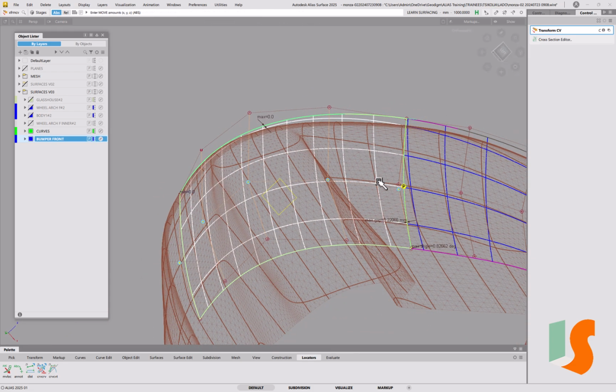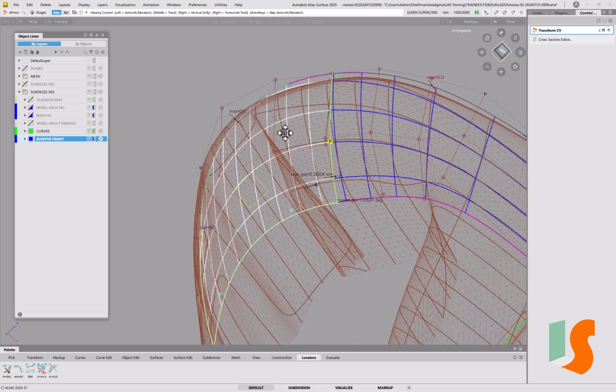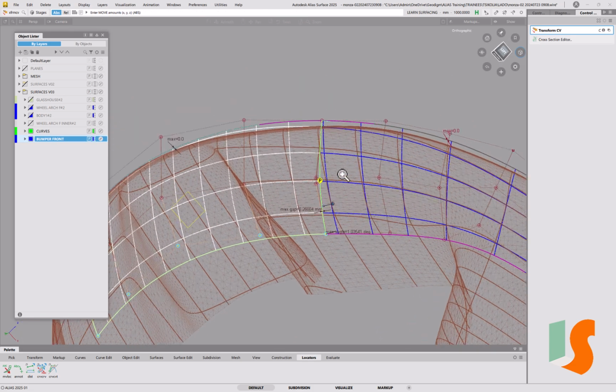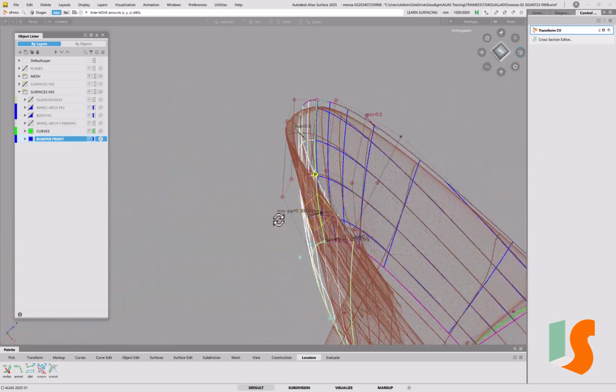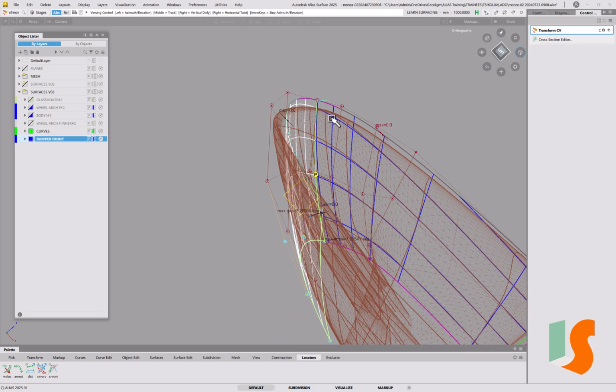similar. Unfortunately, because we are a long way from this, it's going to be pretty tricky, because the original was quite flat, and I've ended up with something that's rather crowned at the minute. Now I could bring this back, maybe bring the whole thing forward. We're sort of having to design this as though we were working from a sketch rather than from a mesh, but this is the problem with working from meshes sometimes, especially because I've changed that top edge so much.